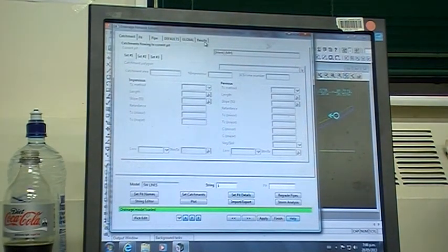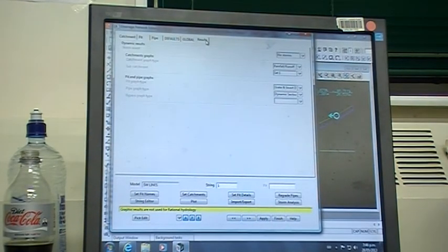As I move from right to left, we've got a results tab. Now this, if we are using SCS curves, is where all the information is presented. It gives us dynamic results, graphs to show the pre and post development flows. Also, I think there are about 35 different options for pumping information out in a nice presentable manner.